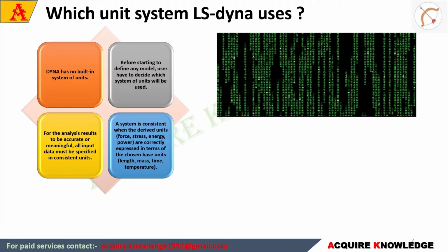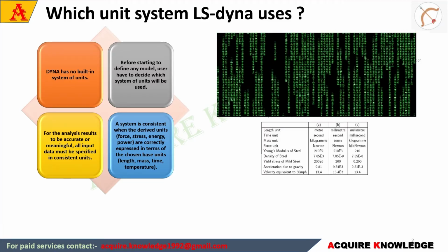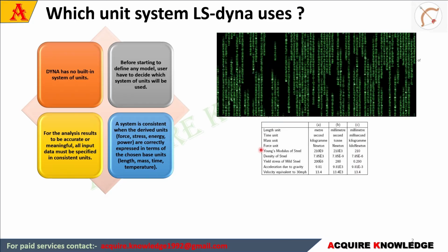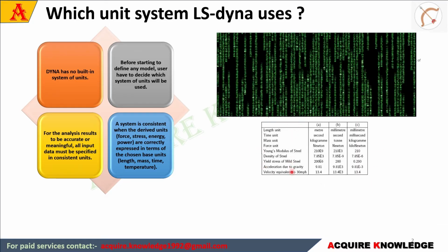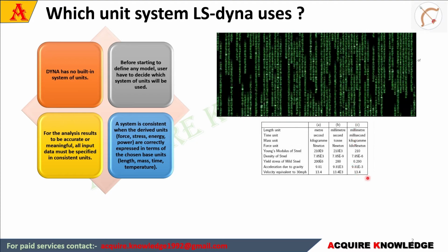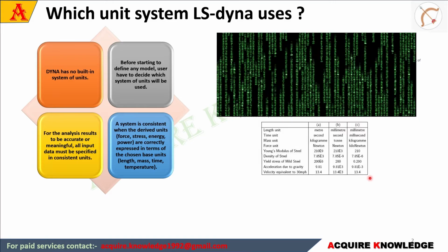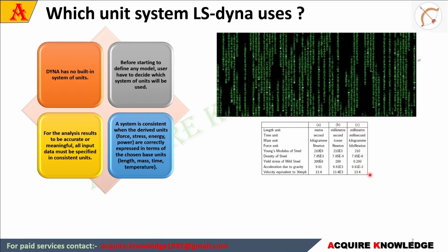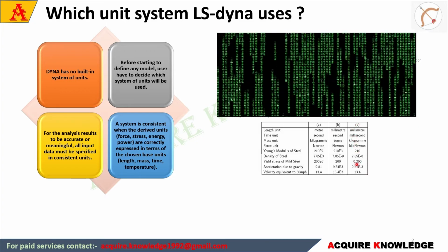Let's take a very quick example. On the right, you can see that there are three sets of unit systems that have been provided for you. I just want to ask: if I go with the third unit system, and we enter a value of 1, how much load is the solver going to apply to the model that we are building in LS-DYNA?